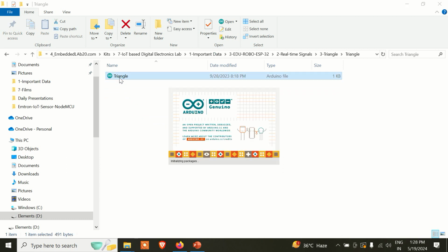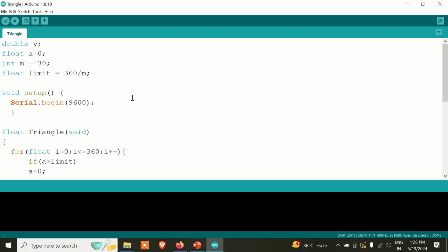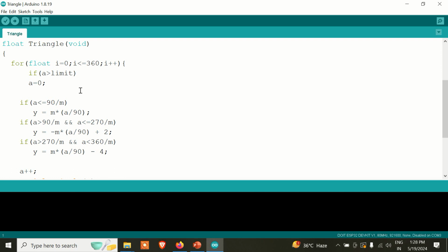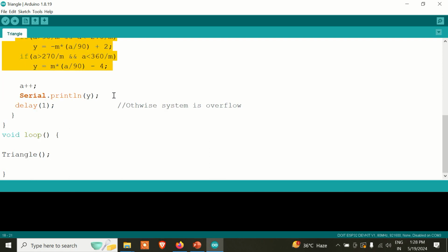In triangular waveform, it's incrementing to a peak max and decrementing from max value both. So it's climbing as well as decrementing. So in this program you can see we have defined the wave, and that wave we have two loops, one for incrementing the count, other is for decrementing the count.